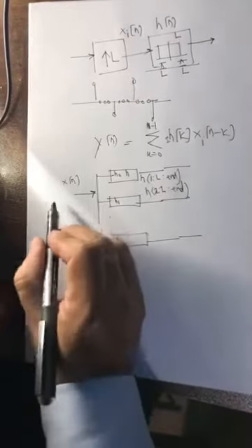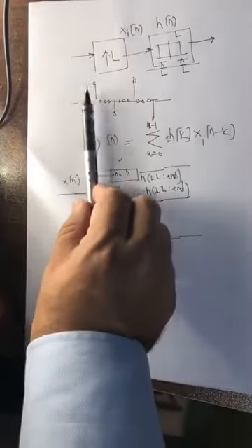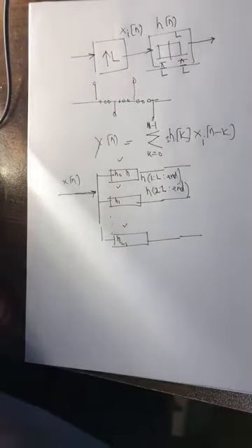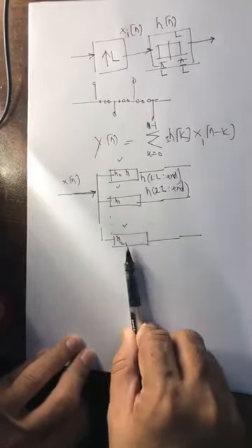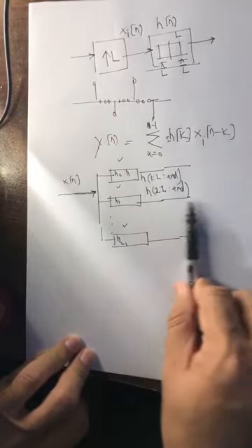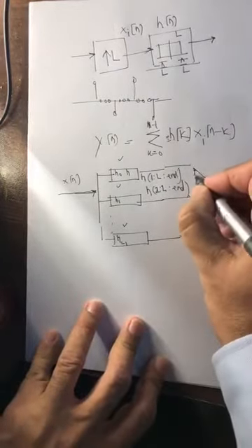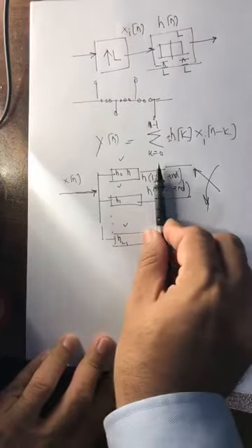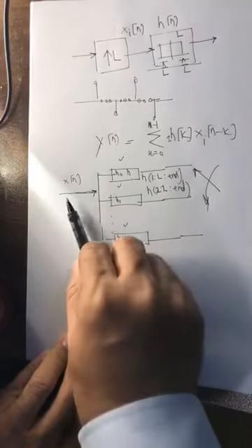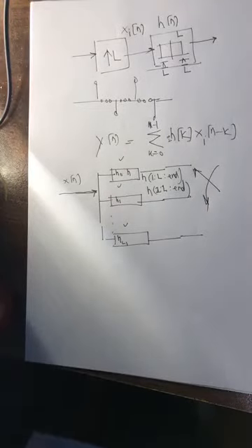And then what you do is you copy your signal to every filter. Remember, in interpolation, for one sample we want to generate 4 samples. For every sample, the output will have 4 samples. So you pass your signal to this copy, copy, copy. So now you have a signal coming here, a signal coming here, a signal coming here, so 4 outputs. And then you put a switch here. One sample in, it goes through all the filters and you get L samples out. One sample in, L samples out. You pick this, pick this, pick this, pick this, and you throw this to the next stage.